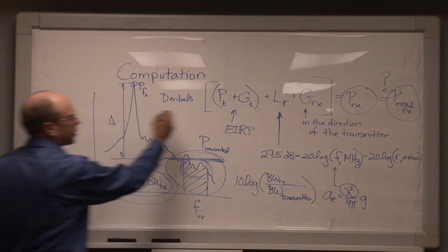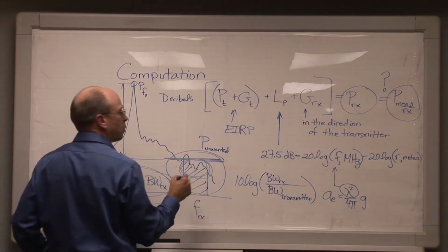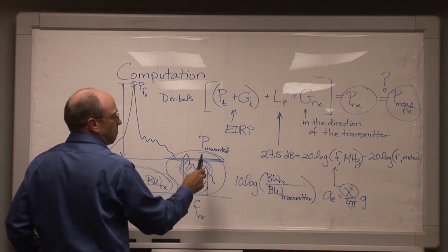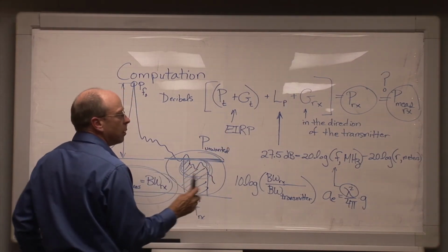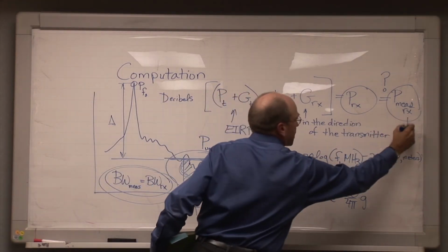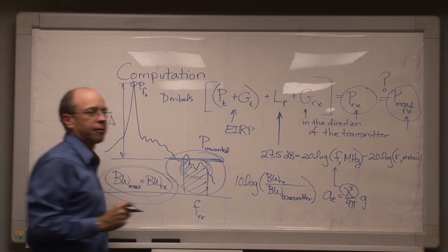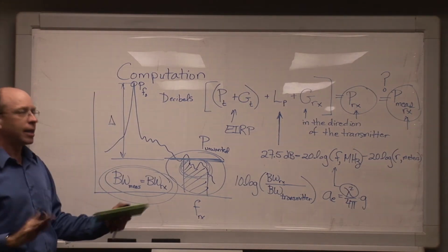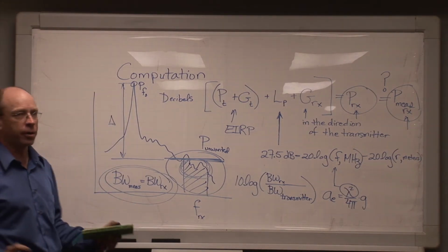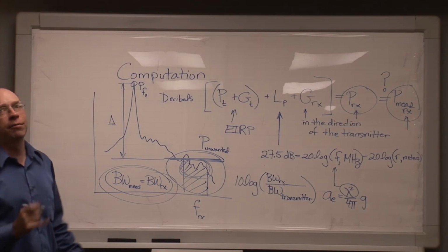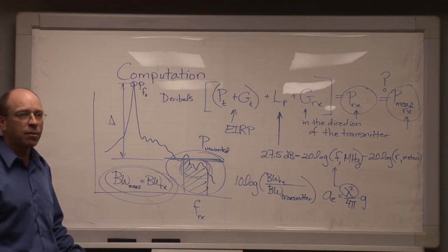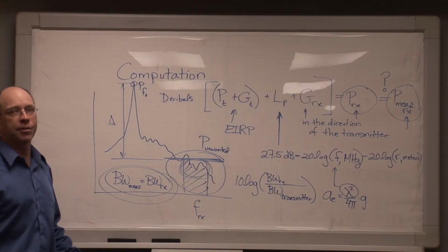If, on the other hand, we do this calculation and we find out that we're getting, say, 30 dB more power measured in the receiver than we can possibly be getting into the receiver from the source, then this is not a co-channel interference problem, because the numbers aren't working out. Now you might ask, how close should we come? Well, I would certainly hope within 10 dB and maybe even within 3, 4, 5, or 6 dB.